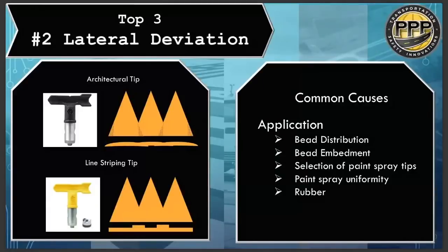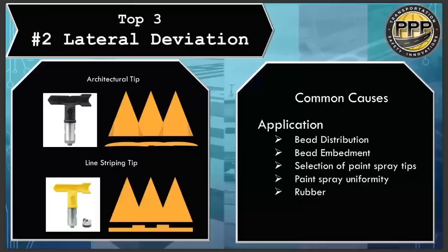With the line striping tips, let's say you have a 6-gun carriage on a truck, contractor, in-house crew, whatever, and you have 6 line striping tips. If I'm doing quality control and setting up this contractor for a quality control strip, I'm looking for a 1/4 inch to a 1/2 inch overlap. That bead of paint gets pretty thick even with just a real small overlap. But that is required because if you don't have an overlap, you have a gap, and that is the worst of the 2 evils. All right, so we'll meet somewhere in the middle on that one.